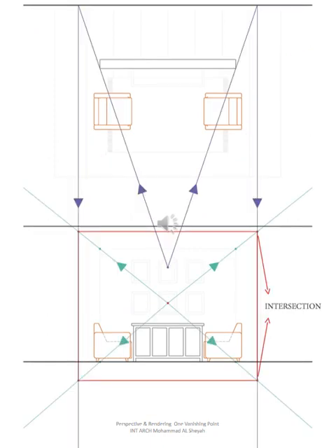We will start drawing the wall using the vanishing point and the station point. Using the vanishing point, we will draw lines to the corner of this wall in the front, and using the station point we will locate the wall in the perspective by drawing a line passing through the corner to the projection line and then going downward.